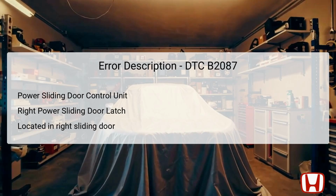The power sliding door control unit serves as the brain of the sliding door system, managing the opening and closing functionalities based on inputs from various components, including the ratchet switch. The right power sliding door rear latch is pivotal for securing the door in both the open and closed positions. Both components are situated within the right sliding door, making their accessibility crucial for effective troubleshooting.